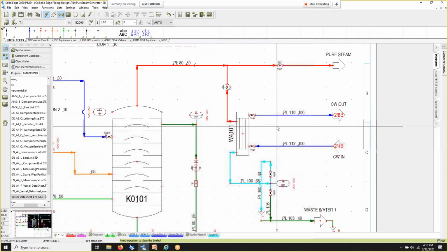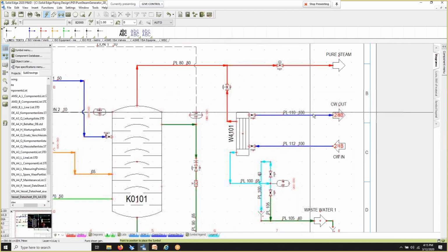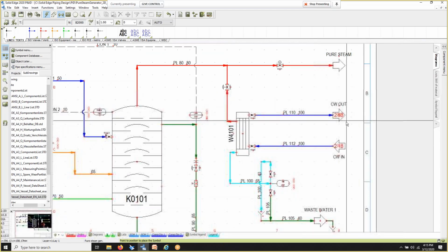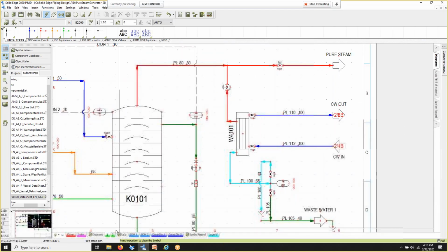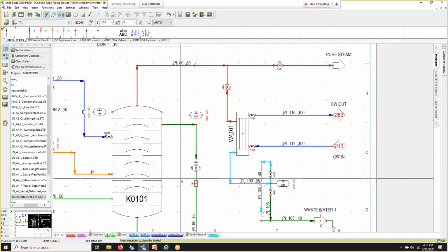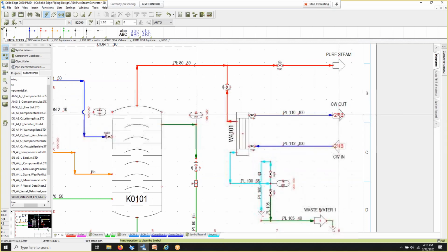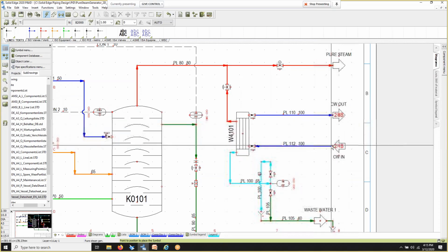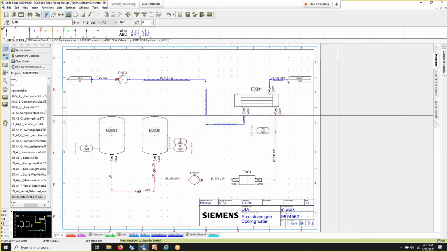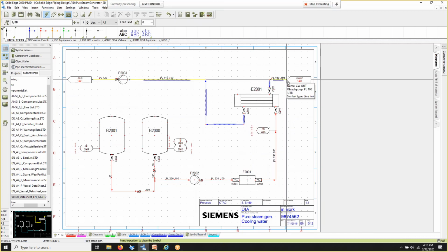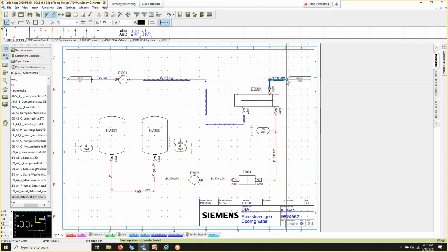Now, in addition to all of that, very often you might run out of room on one page and need to continue on to another. In my case today, we're only looking at 2 diagram pages, so not very hard to figure out. But again, very often we might have, is it sheet number 2 or is it sheet 42? And keeping track of that can be a challenging task. So we can actually have these line links over here to tell it where it came from or where it goes to. Double clicking on it will put our mouse cursor where our pipeline continues on the subsequent sheet.